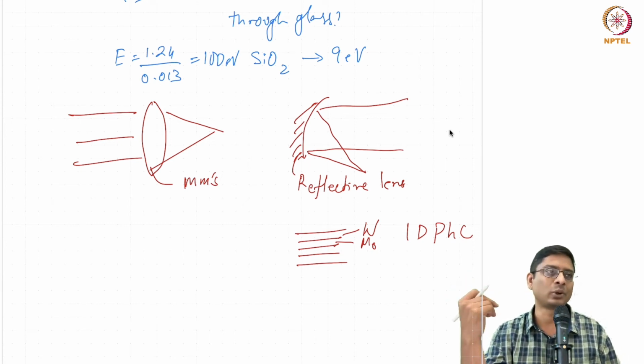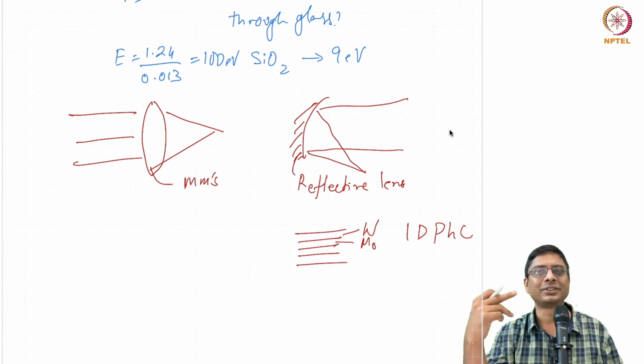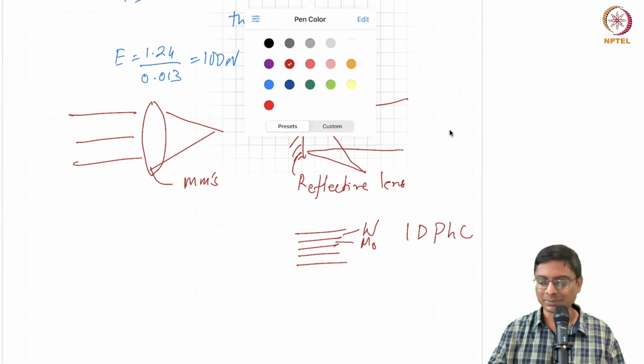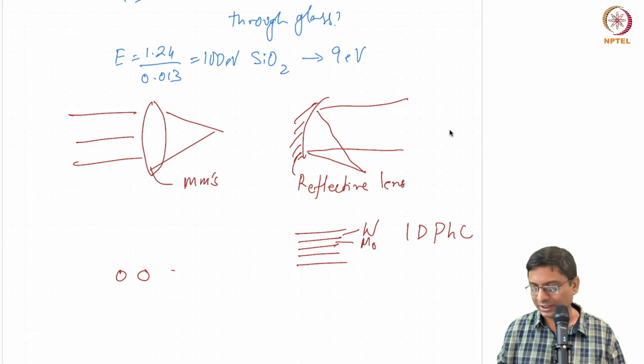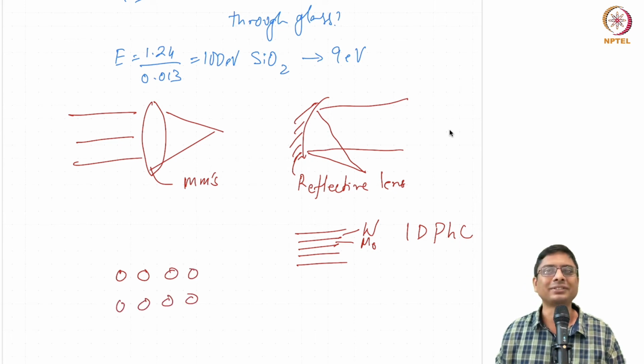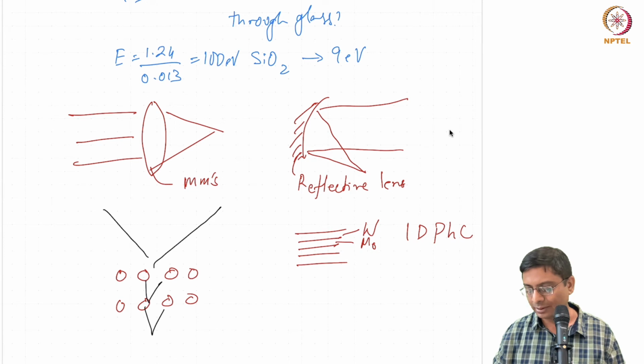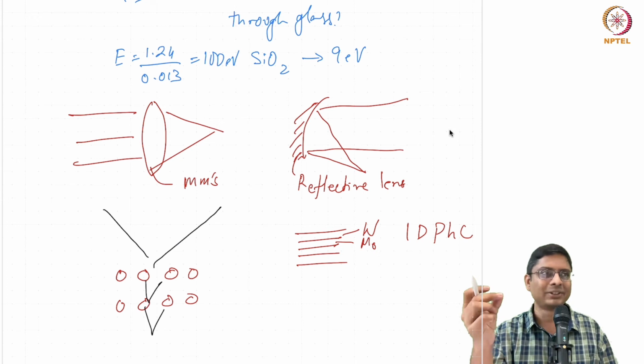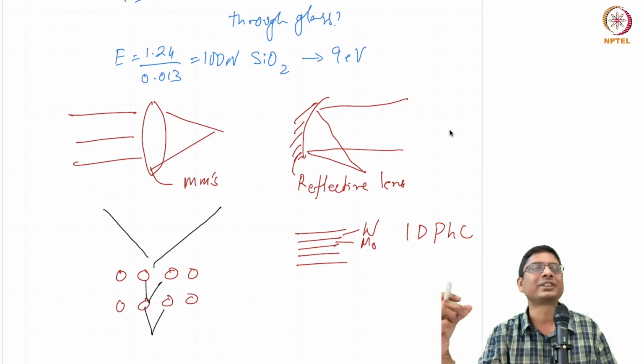Of course it's going to be in what thickness range? It has to be thin. Because, remember always, this is, in a way, even your lattice, right? I'm sorry, I'm diverting a little bit. I hope that people will excuse me for this. But, you have silicon atoms, right? You have X-ray diffraction. What is X-ray diffraction? You have light incident and it's getting reflected. From all these multiple reflections from each plane, they come back and add up in phase and you get diffraction, right? So, atomic lengths are angstroms. So, X-rays will get diffracted. So, you have to put nanometer scale. Maybe 5 nanometers or so, 10 nanometers.